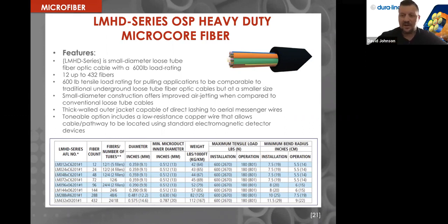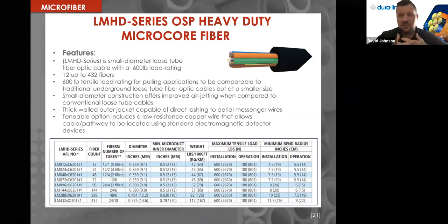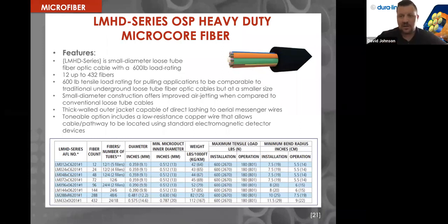ratio. And to add on to what Tim was talking about, less condensation, less water. Because we're filling those ducts up pretty much to almost max capacity, there's not much volume of water that even gets in there. So even if water were to get into that microduct, and freeze, by all means, it's not thick enough as to where, if you have a 2-inch conduit with a lot of void space, that ice will expand and possibly damage that existing fiber. It doesn't happen at all with a microduct, just because of the fill ratio that you're doing with that.